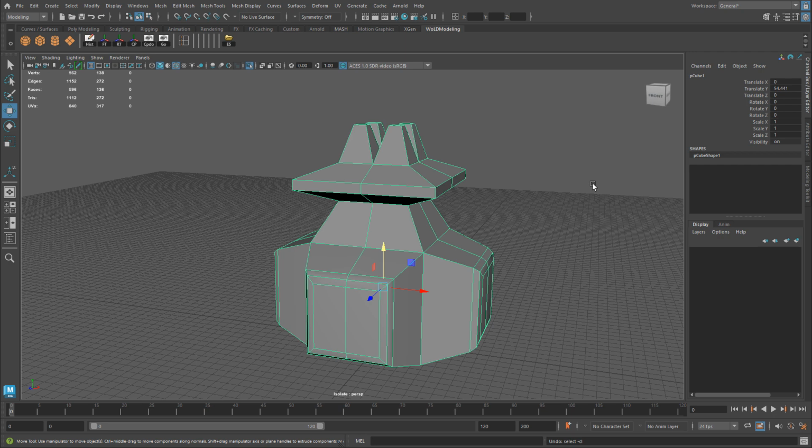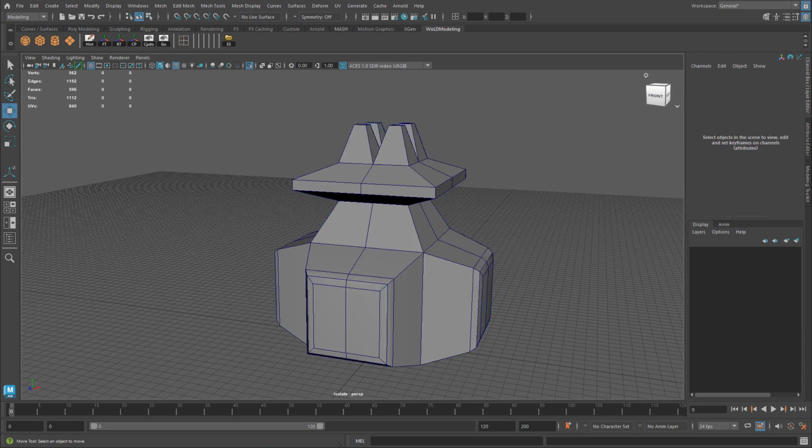Go ahead, set up at least one project to work from, and that way you know where everything is going to be kept and everything will be nicely organized for you to work from, save your files into, and back anything up you need. Number 5, you should save as an MA file type instead of MB.